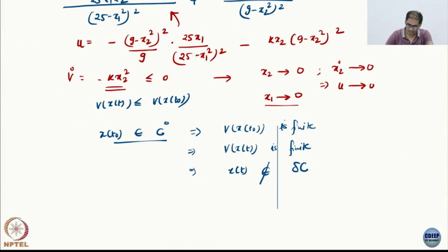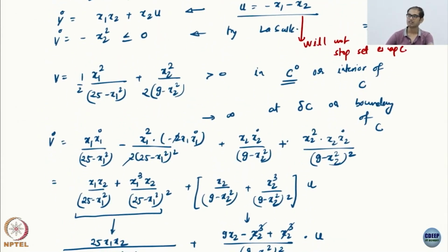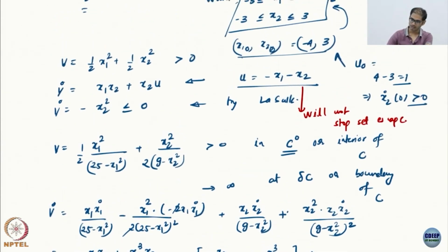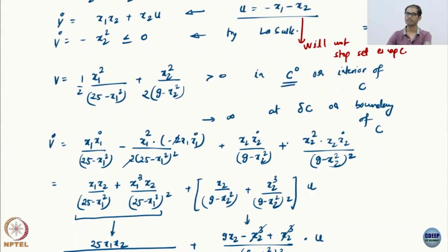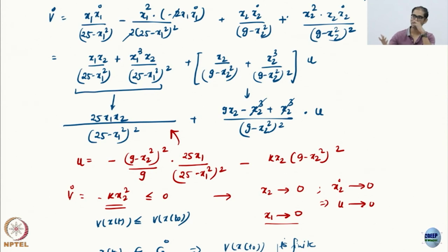So you see, by making this small change in the v, of course I chose a different, complicated control corresponding to the v, this is the Lyapunov redesign, but I was able to ensure that the trajectories remain inside the set, and you can verify in this case. You can try all these tricks that I tried, but you will never get out of the set. So this gave me a safe control. This is what is called a safe control, right? You remained inside a set that you desired, the set C.